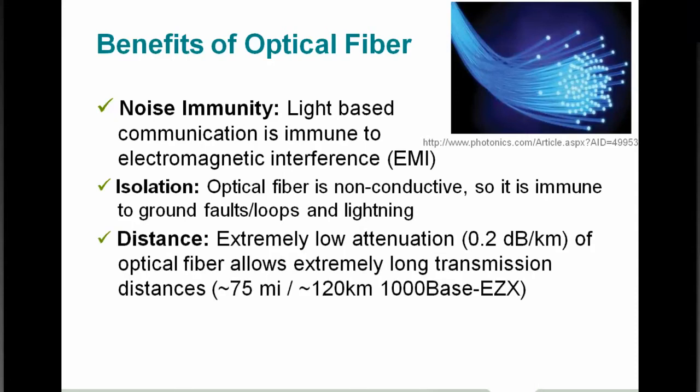And then lastly, and I guess this is inherent with our discussion today, you have extremely low attenuation in fiber optic cable. Granted, there are a couple different types of technologies for driving signals on that, but fundamentally, you can go long distances. We're limiting today's scope of conversation to the more common off-the-shelf technologies. But when we're talking about commercial off-the-shelf technology to take Ethernet and, with a drop-in box, connect it to fiber, you can see distances up to 75 miles, which might be used in a transportation or a municipal type application.